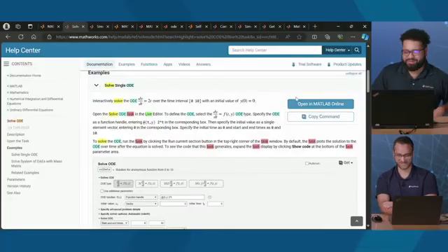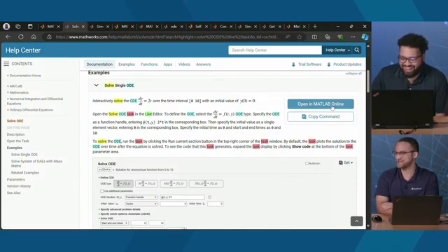The other thing about Simscape is you can also import CAD. The caveat is you have to have a good CAD model, well made in the sense that the mates have to be good. We have something called the SimMechanics Link, a product that will take your CAD, convert it into a Simscape version of the CAD, and then you can use that to build your digital twin. I believe that's a new product now. It's Simscape Multibody. Yes. So make sure you're looking for the right thing. We change the name sometimes.